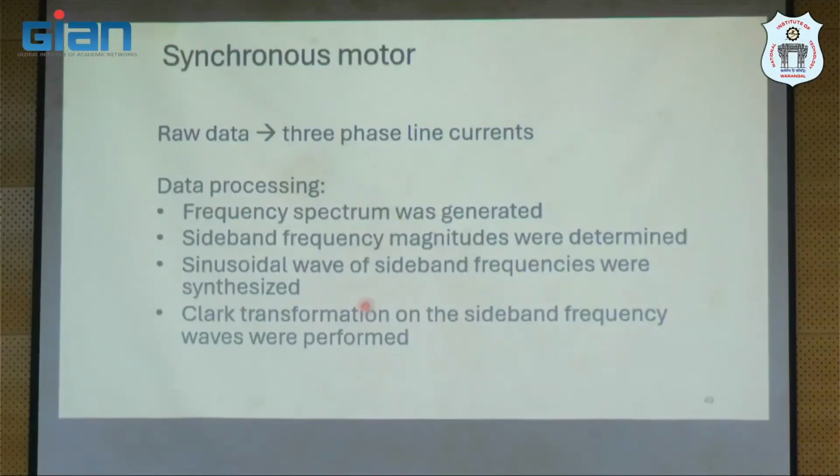So for synchronous motor, three-phase line currents were captured. I did a frequency spectrum of the individual line currents, and I picked the sideband frequency components. Based on MMF specific permeance analysis, I know that whenever there is eccentricity, certain sidebands will appear. So I picked the magnitude of sideband frequencies, and then I did an inverse transformation from frequency domain to time domain only for sideband components.